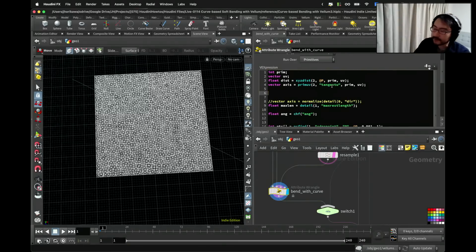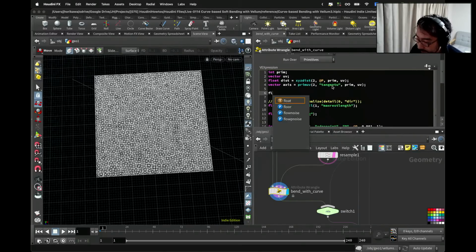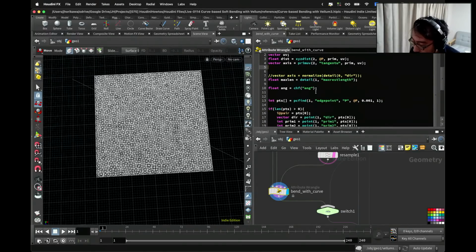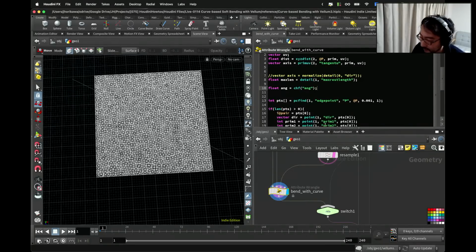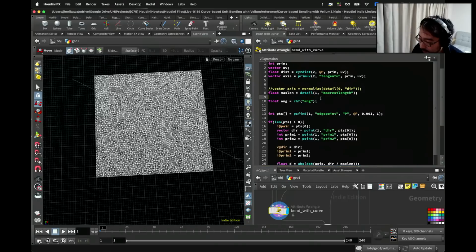and I'm going to use it for an angle probably. Let's create a map function. An angle is calculated right here as a constant value. So I'm going to remap this distance to an angle using minimum and maximum distance to a minimum and maximum angle. Makes sense?